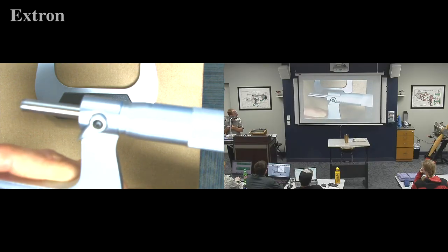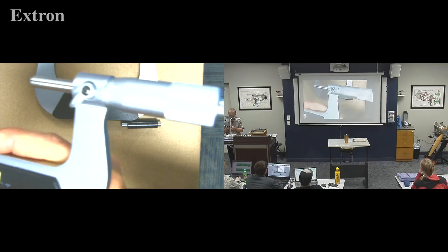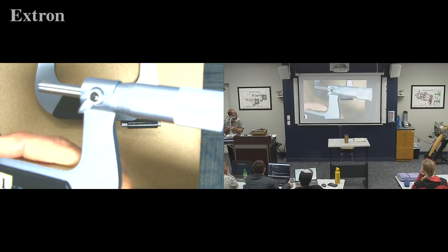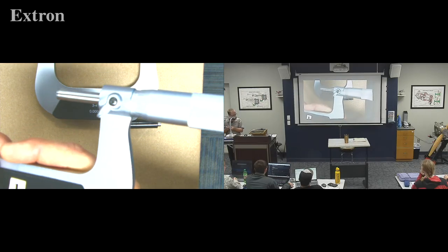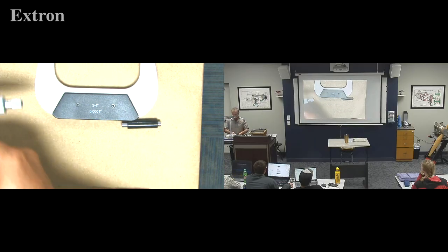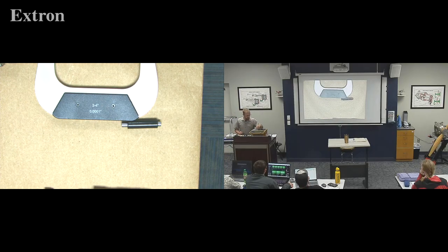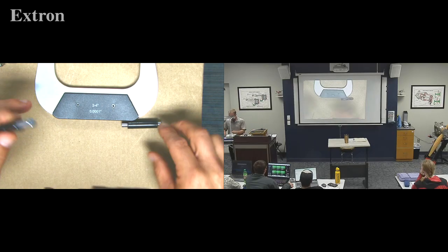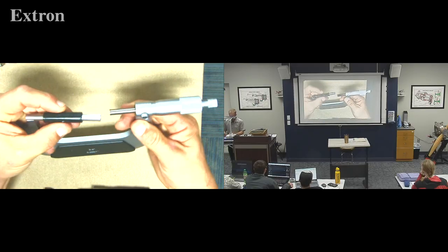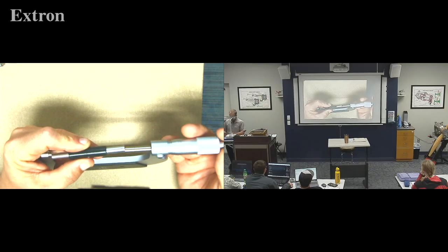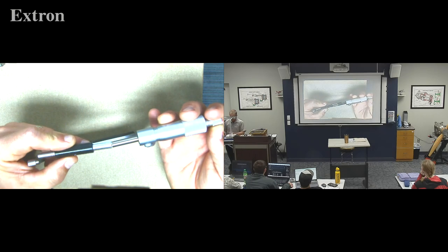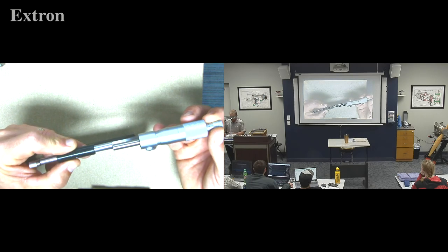Can you see it? I am just barely off, okay? It is almost dead on 0. So, you could adjust that one just a little bit, or you could retry it again just to make sure that you were perfectly on. But let's get over here and see if we can find one that's way off, just for fun's sake, and I'll show you how to calibrate a micrometer. Before you're measuring pistons and everything else, you want to be able to calibrate one correctly. And then make sure it's not diagonal like this, because it will be wider than it should be.